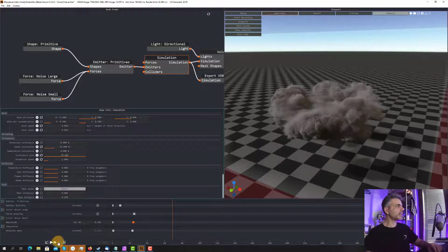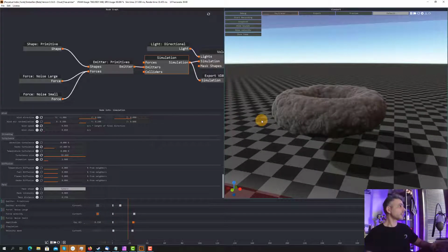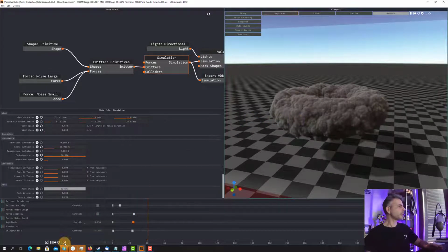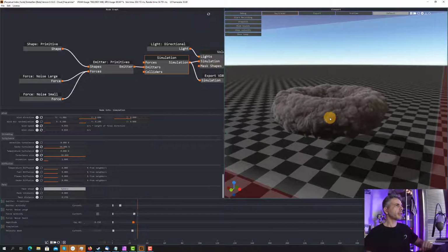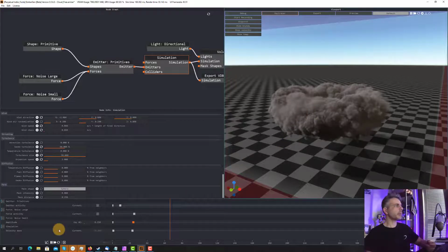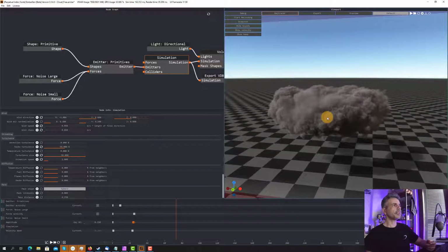Maybe 100 is too much. Let's go to 25 because I like to have a slower simulation for the smoke turbulence, but maybe 25 is too slow because it's not so visible, and I don't want to simulate too much frames to have the cloud. So let's try with 50, and we should see the areas as before. Okay, you see that something is changing here and here too, and other areas have a higher density. That's really nice. Nice. Okay, let's move forward.